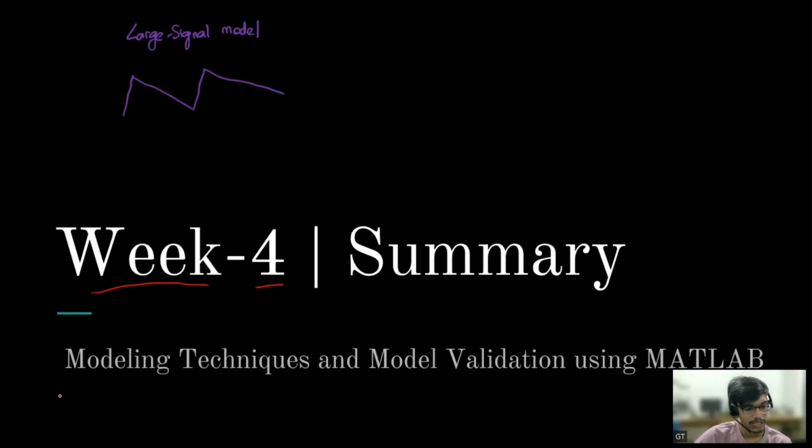Okay. So large signal, what we have done is, say I have taken a sample here. Using this sample and the equations, I am getting an expression for the next sample. So this is xn, this is xn plus 1. What the large signal model does is give me an expression of xn plus 1 as a function of xn and the input. Usually our input is only V. There can be a load source at the output. For the time being, assume there is no load source or current source. So we are getting xn plus 1 in terms of xn.